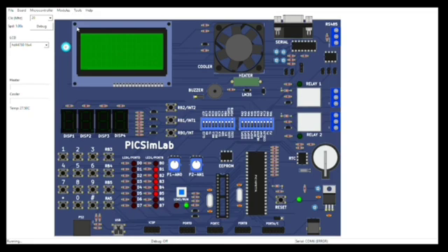The build generated a hex file in a particular destination. As you have seen, the XC8 compiler has compiled the whole program and generated a hex file. Now we will be loading that hex file. So we have reached the destination and we can see the hex file here. I have loaded the hex file, and as it shows, we should press key 5 to turn on the washing machine. So the washing machine has turned on now.